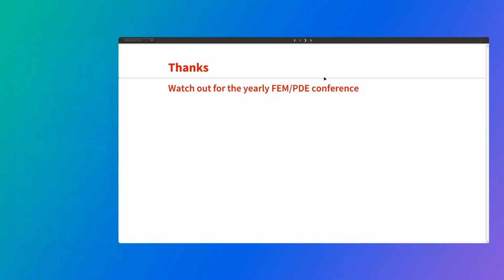Another question: I was wondering what's going on behind the scenes that improves the performance of a PDE component compared to its explicit analog. Okay, so I assume the question is that you have an example where the PDE is solved more efficiently when you use a PDE component compared to when you type it out manually. The reason I could imagine is that the PDE terms that we generate with the PDE coefficients fit very well with the PDE parser that we have, so they're optimized for that, and the PDE parser can make efficient code out of that. It shouldn't be a whole lot of a difference, but I can imagine cases where it can become a difference.